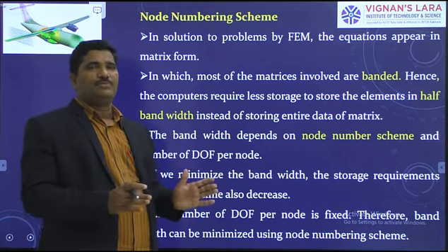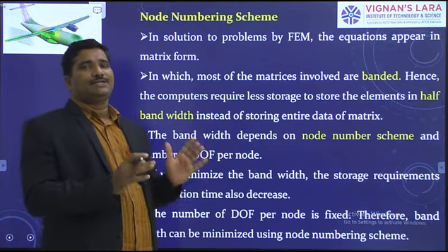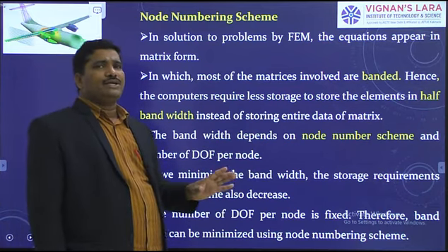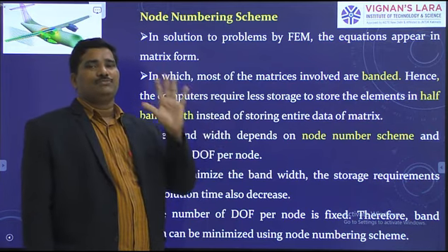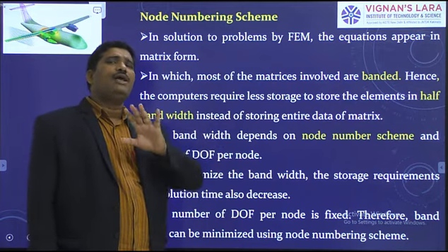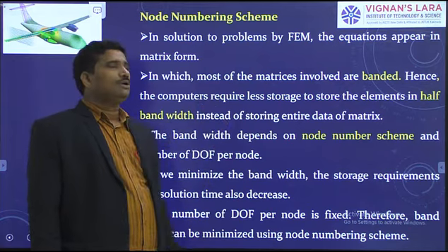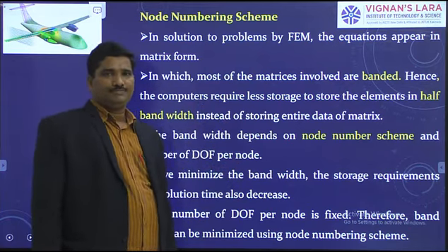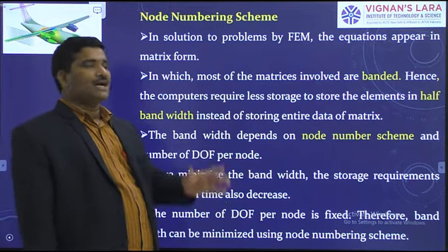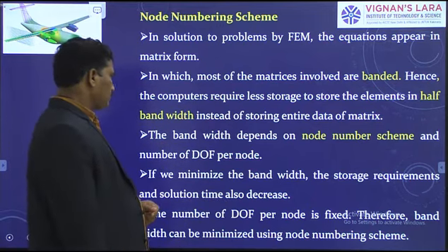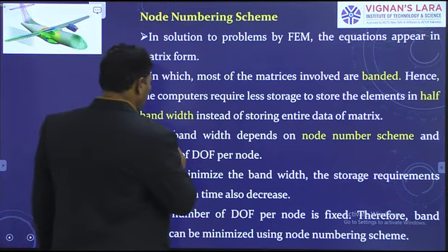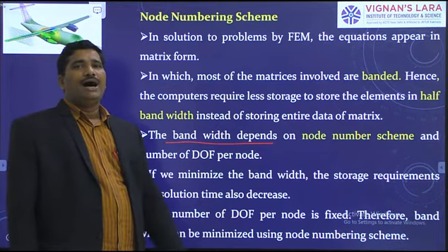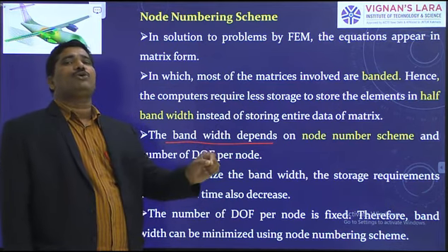When we solve a problem by finite element method, all the equations appear in the matrix form. In most of the problems, all the matrices are banded. Therefore, you need not store all the elements of the matrix in the computer, because the matrices are banded. The bandwidth depends on the node numbering scheme and the degrees of freedom of the node.